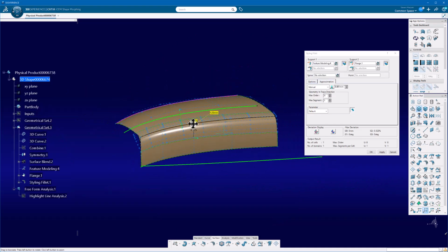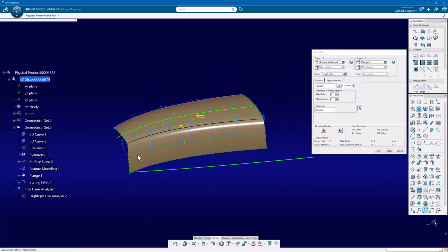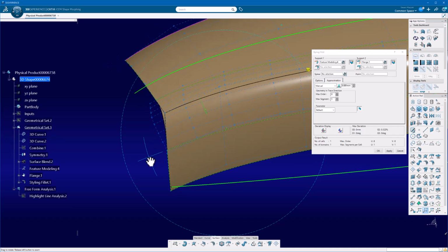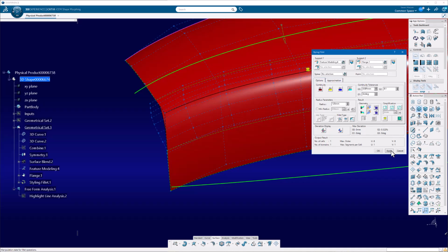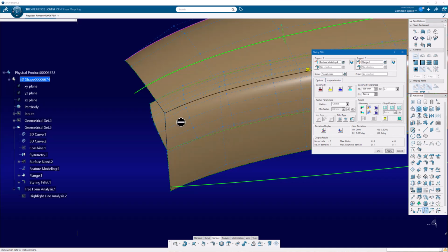And somebody will look at this and go, well, why is this overhanging over here? For the newbies, people that don't understand, I told the system to trim that blend. Right, I want to extrapolate to the edge, and then relimit, so I end up with this. If I don't have the relimit on, you'll see that blend runs all the way out long.